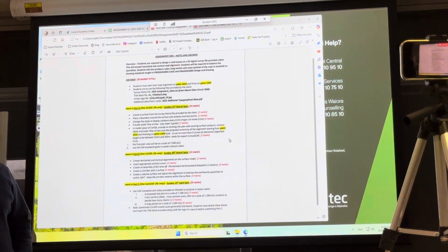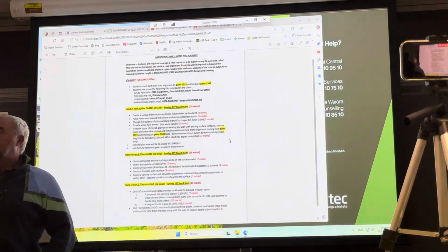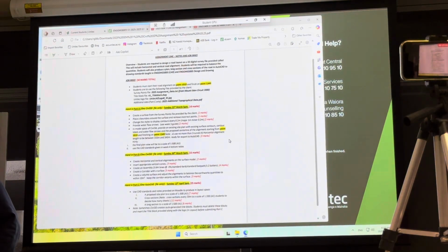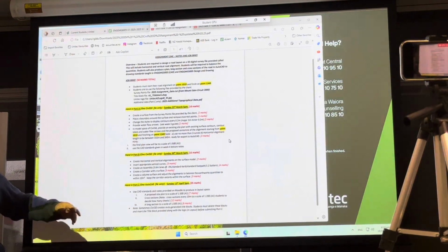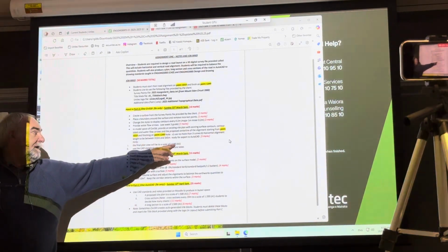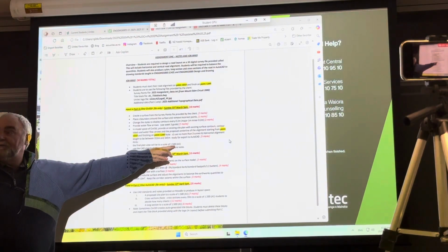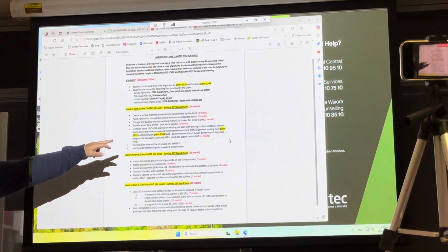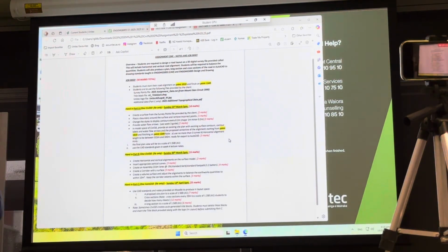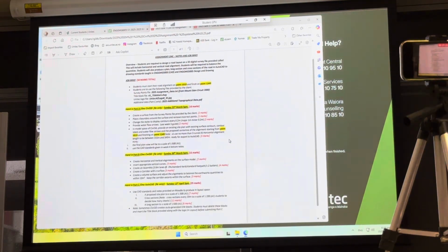What you're having to do though is, tonight, when I go through my CAD stuff, I'll just remind you how to work out the text heights. And you'll have to work backwards from that to work out what text heights you're going to need at 1 to 500, a la design and drawing. So once you've figured that out, it's not a hard sum to do. I'll show you in tonight's notes.